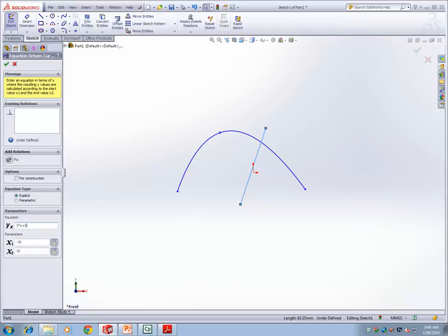Even for gear profiles which look like involute profiles, which are convex and concave shapes, but they have a certain equation to follow, we can insert the equation here. Once the equation is inserted and you put your limits for that equation, it will keep drawing the lines, or the curves. Now you can put your quadratic equation, parabolic equation, hyperbola equation, whatever it is, and you can draw them, rather than inserting as a standard entity.